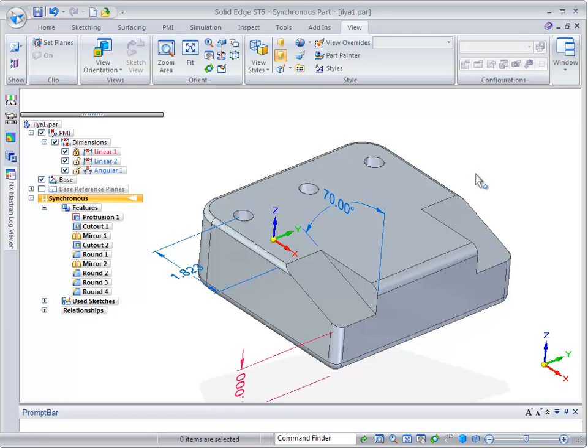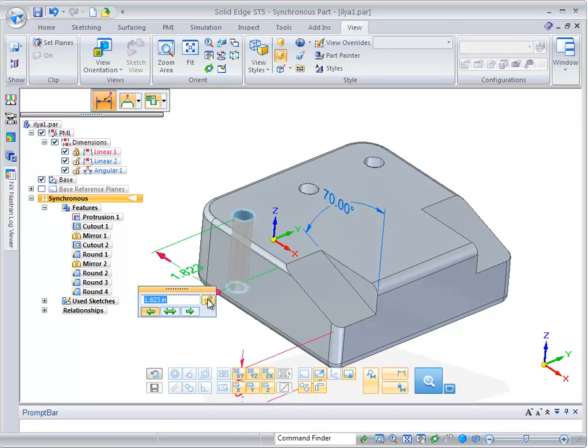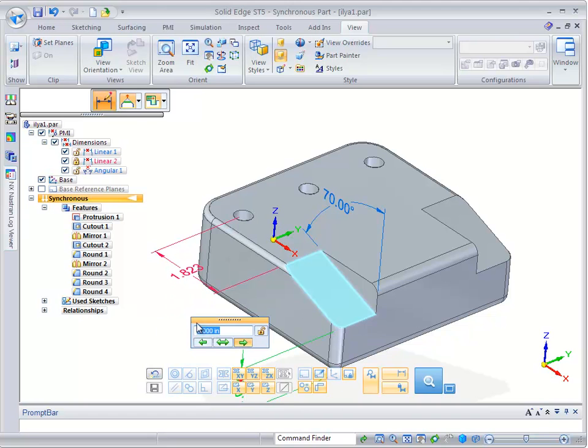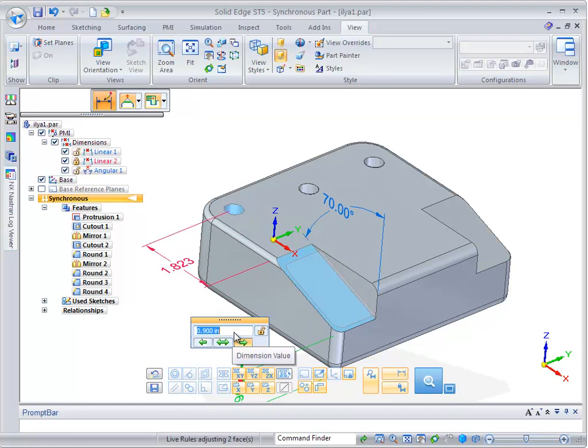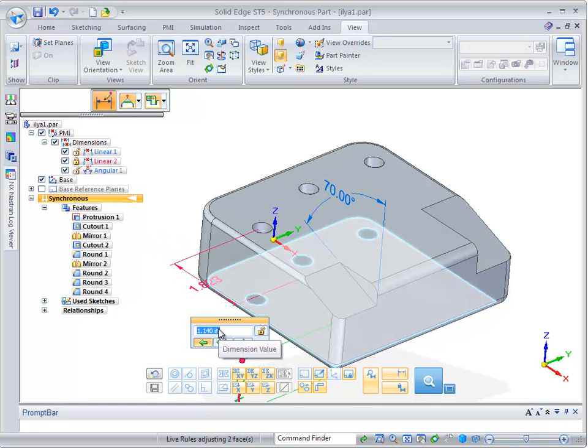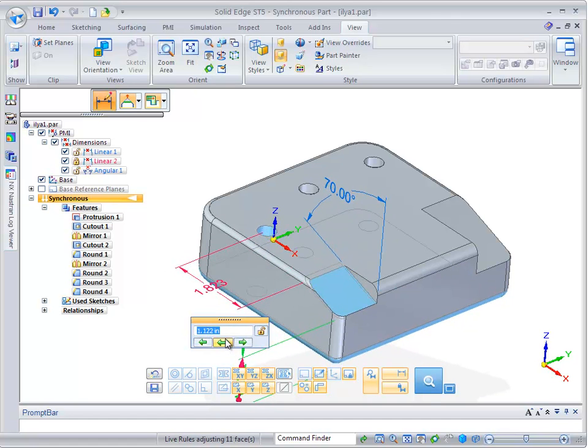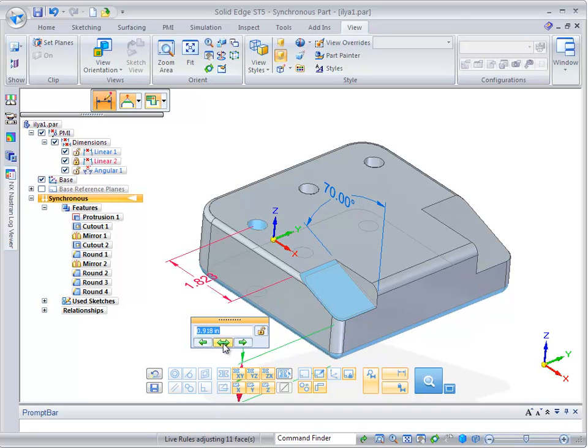Okay, here are a couple more tricks that you can do with design intent in Solid Edge. Before, we had this dimension locked and this lower dimension unlocked. And when we make a change, the change happens depending on the direction of the arrow, or if we have a symmetric change that we want to set up. Notice that this symmetry happens without any sort of symmetrical plane or anything like that. It just happens equally to both sides.